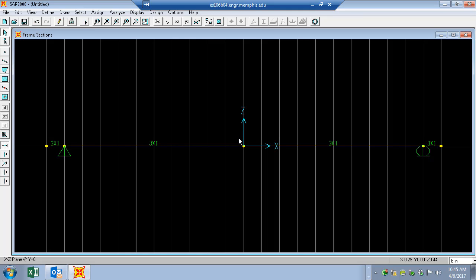So since we're measuring in this direction, and this thing is 10 inches, our first value would be at x equals 0, the load is 0. And then here at x equals 7, the load is 0. At this one, also at x equals 7, the load would be what? Minus 40, right? Pounds per inch. And then at this point, it's going to be at 10 inches, also minus 40. You guys see that strategy? So with these 4 coordinates, I will open up that menu, we'll enter those in, and you'll see this draw on the end of the element.